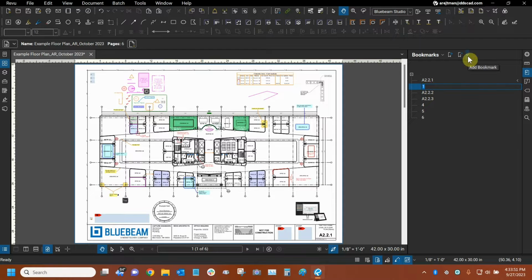And there's a drop down here that we'll look at very soon that gives us more flexibility on that. So right now I can call this bookmark test bookmark and then press enter. And it's basically done. It's also basically useless because if I select either this one or the test one, nothing seems to change whatsoever. So we don't really need this one. Now I could right click on it and delete it, as you can see, but instead I have a really cool option called Set to Current View. So I'm going to do that instead.